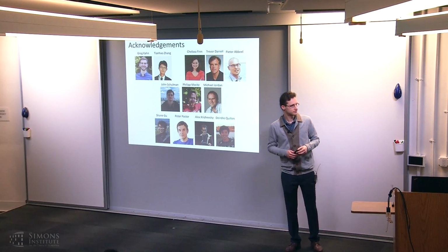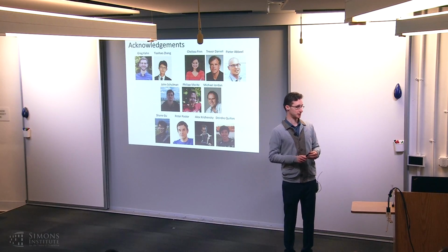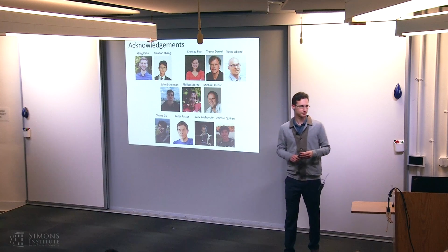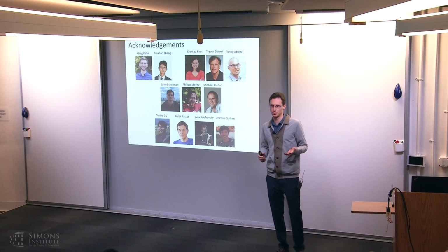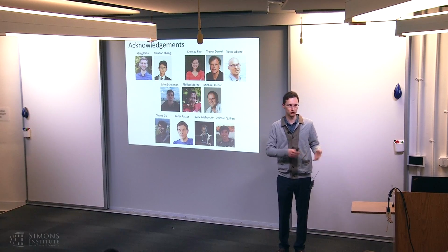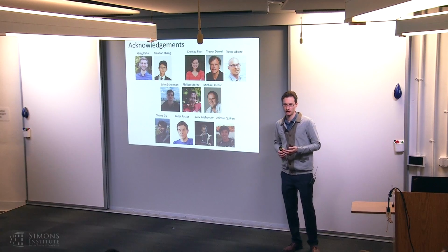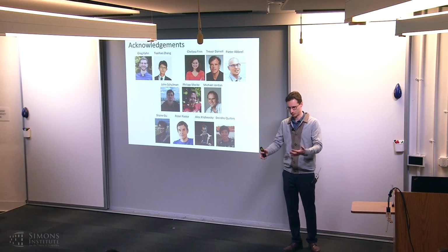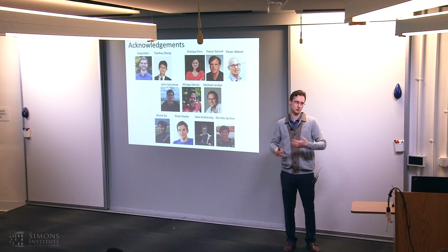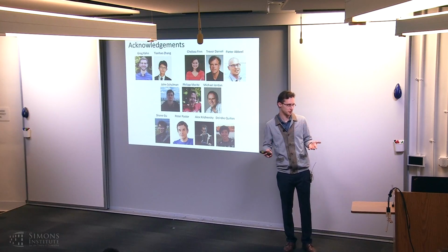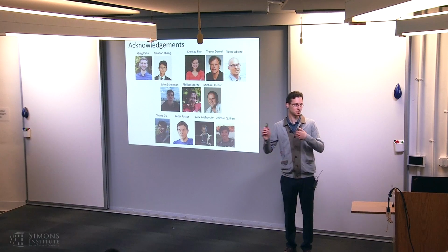Is imitation learning just a single algorithm, or are you allowed to...? Imitation learning is a class of techniques. Class. Yes. You could design your own. Yes. But there are different properties that an imitation learning algorithm can have. So DAgger is an imitation learning algorithm, but it requires you to collect additional data. The NVIDIA thing that I showed is just using a very, very simple, naive imitation learning algorithm where you just take your data set and you train your neural network on it. That's also an imitation learning algorithm. It's a simpler one without any concrete guarantees on performance, but fewer assumptions because you don't need additional data.